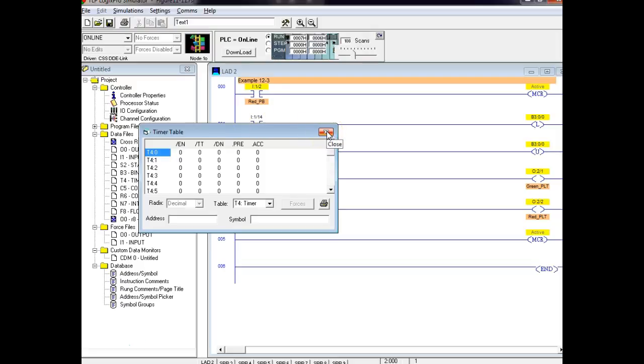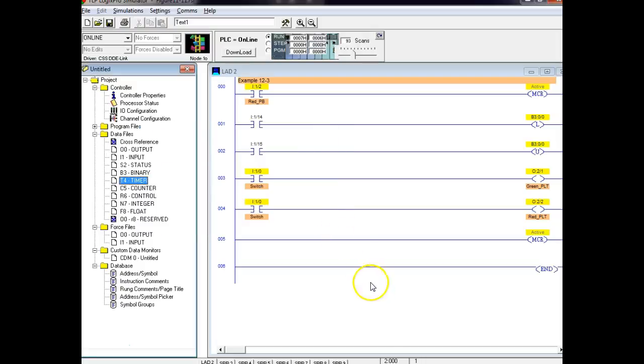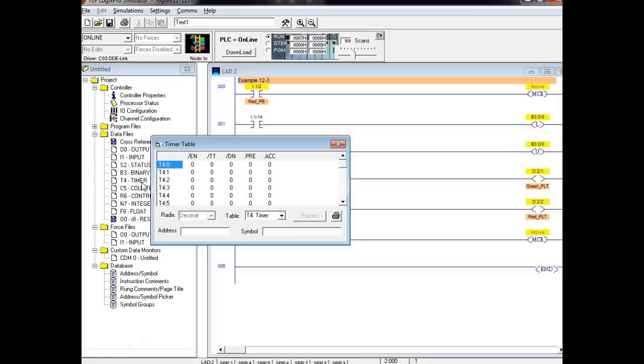Yeah, they come on as soon as they energize. But I say some of their timers, I don't know if their high-speed counter has an enable bit. I'm not sure. PRE and HSC are the only ones you put a dot in front of. The other one you put a slash in front of, because it's a bit inside a register.